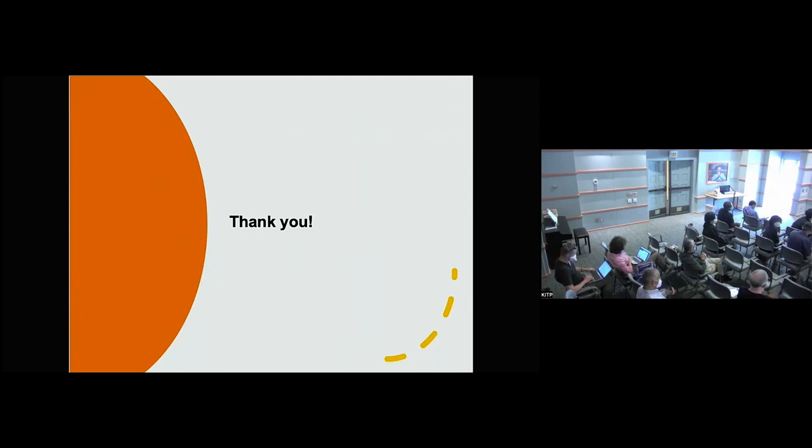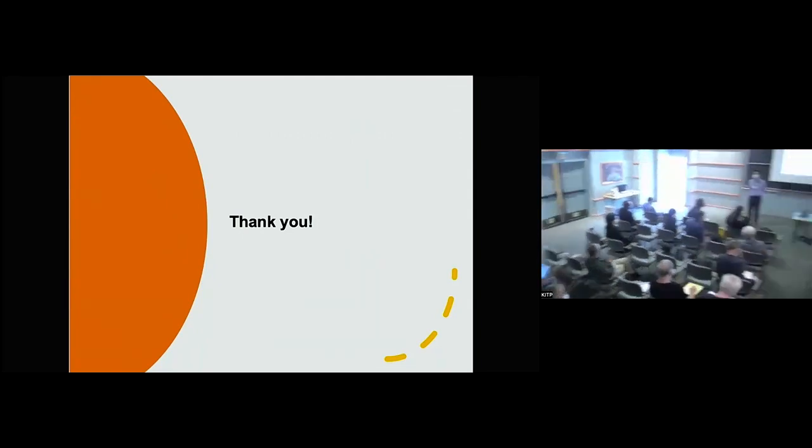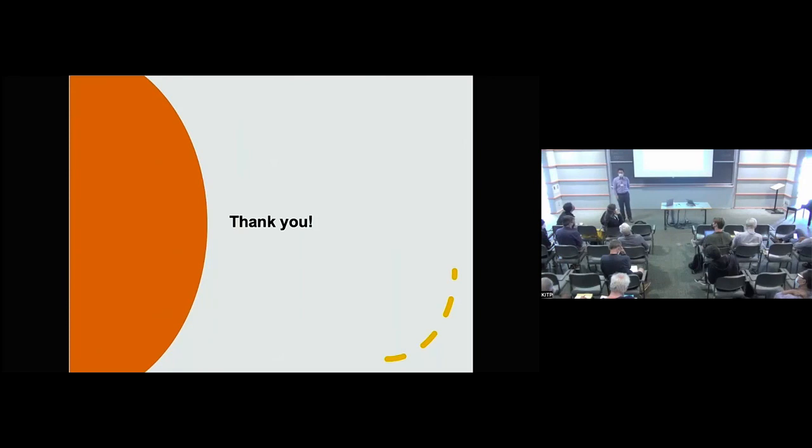So the thermal evaporation limit is about 1.4 or so, right? Yeah. And also, as you realize, the Guihua Yu group's hydrogel already almost doubled that. For our work, we used carbonized cow manure, and we already achieved up to 5.3. That's almost 2.5 times. We tried to explain the fundamentals, and as we explain in that paper, it's still not clear to us. It came with the reduced latent heat of the porous materials. This is the only way we can explain that.